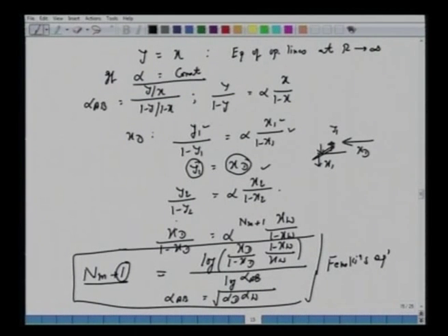All right. So as an exercise, you can try this. Start from your top of the column, xt, then y1, x1, then you have y2, x2 in equilibrium. So every time you write down the equilibrium curve equation for this, and for the operating line, every time you write y equal to x. So with these two equations, by successive substitutions, one can obtain an expression for the minimum number of plates, including this reboiler, in terms of known quantities like top composition, bottom composition, and the average relative volatility. Okay. So this is what we have for the total reflux.